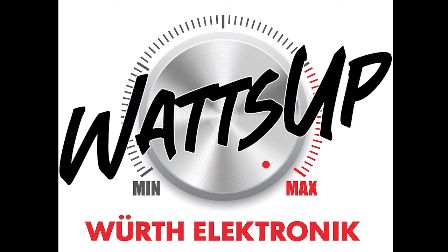Next, we're going to take a look at the type and the EMC. Magnetically shielded power inductors, such as the WE-PD or the WE-HCI, are recommended for EMC critical applications. The shielding prevents uncontrolled magnetic coupling of the windings with neighboring conductor tracks or components. Now, this gets us to our fifth design tip, which is use a magnetically shielded power inductor if at all possible. Do not route any conductor tracks under the component and do not place any circuit boards directly above the component, as this could give rise to coupling via the air gap remaining.